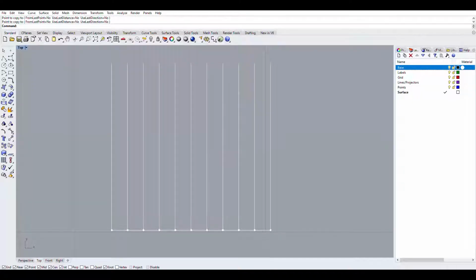Down here, that's kind of important. These are all going to be control parameters for how you interact with your objects or curves or surfaces inside of the program. So if we have midpoint selected, let's just say I have a line, I'll be able to see where a midpoint is. It'll snap to a midpoint. And if I take midpoint off, it won't really tell me what the midpoint is.